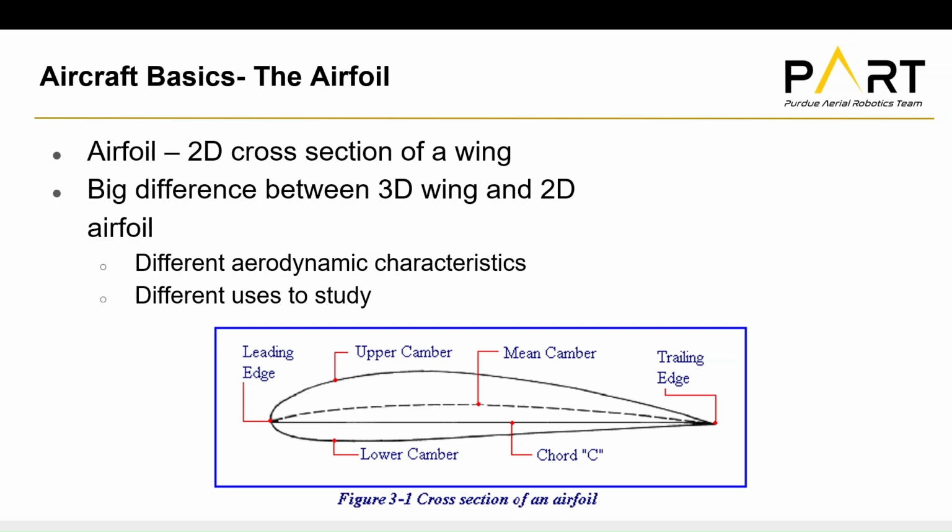So we would look at an airfoil like this and we'd say, okay, well, this NACA 6415, which is a type of airfoil, it's just numbers, which we'll get into, showing how an airfoil looks. And you see that NACA 6415, you say, okay, well, this NACA 4415 has lower lift at a certain angle of attack. So that way you can look at the different airfoils and determine which one would be better for your wing, right? Generally, you want to look at a high efficiency airfoil, or if you're doing a short takeoff plane, or like Dodo was, where we wanted low stall speed, you would be looking at a high cambered airfoil.